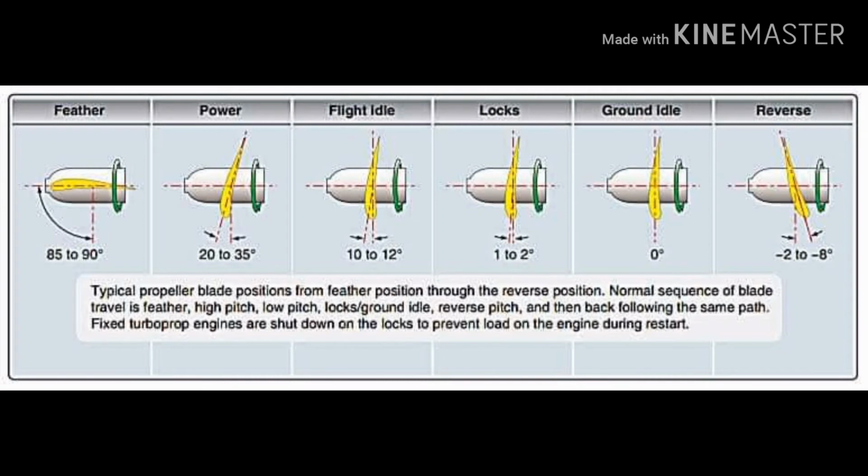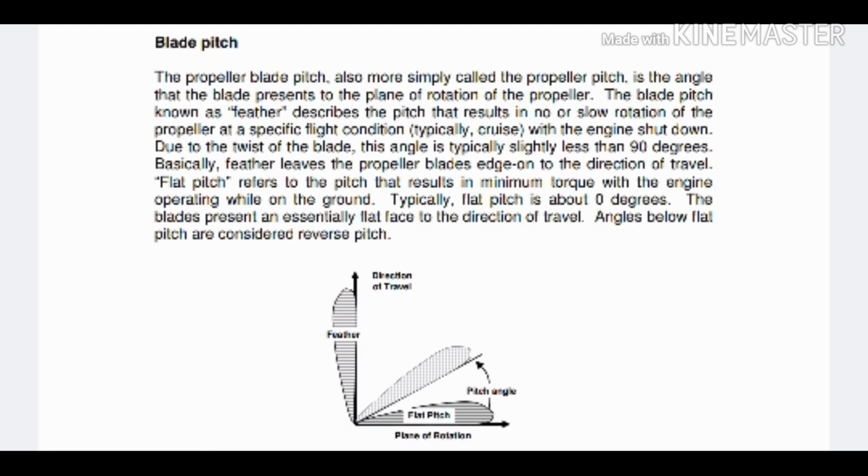One of the principal causes of loss of airworthiness in propellers is corrosion. External corrosion on metal blades, hubs, and other components poses a serious problem. Internal corrosion may exist where moisture may collect in internal cavities such as hubs, blades, clamps, and pitch control mechanisms. This threatens propeller structural integrity and performance without being noticed.